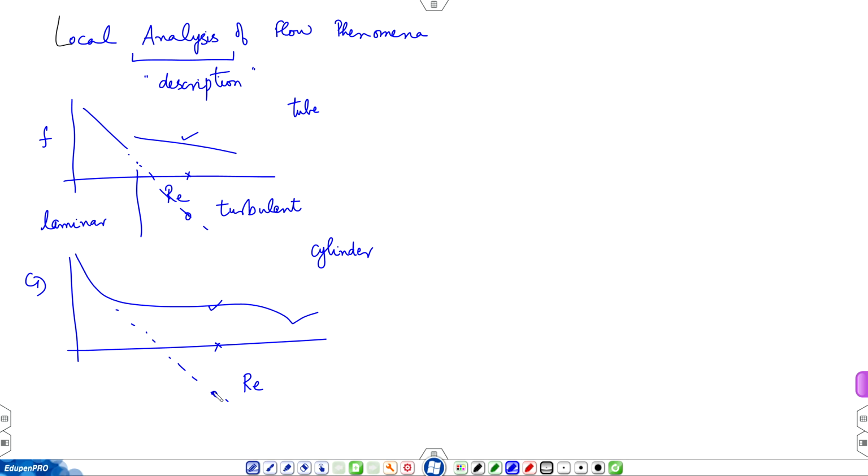So, depending on the Reynolds number, disturbances can increase friction factor by let us say 10 times, maybe even more. And this friction factor is what determines pumping power. So, the increase in pumping effort can be substantial. Similarly, the force acting on the object can be substantially large. If you think of let us say a self-propelled object and it encounters drag, if it is 10 times higher, it means the fuel that you supply for propulsion is also 10 times higher, substantially higher. So, these have profound consequences in applications.